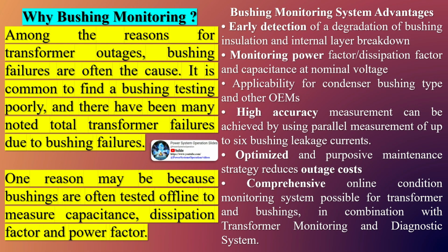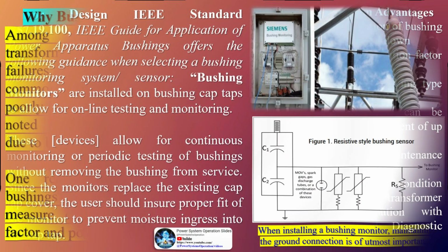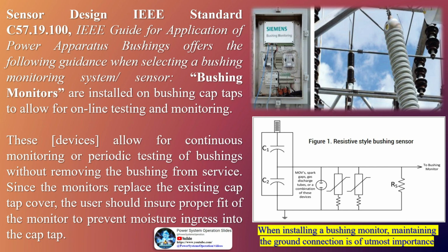The innermost conducting layer may be connected to the main lead, in order to increase the radius and reduce the electric field in this region, also reducing the intense electric fields that may be caused by surface roughness on the main lead. The outermost conducting layer is connected to the flange of the bushing that, in its turn, is grounded. The intermediate conducting layers are insulated, with floating potential.